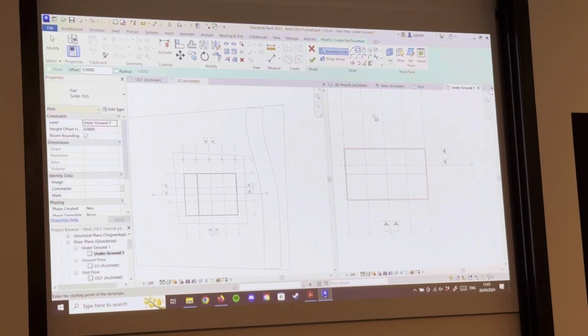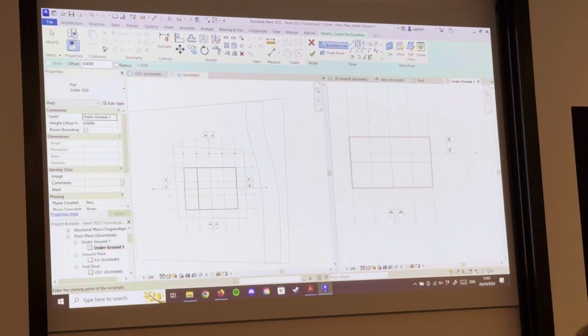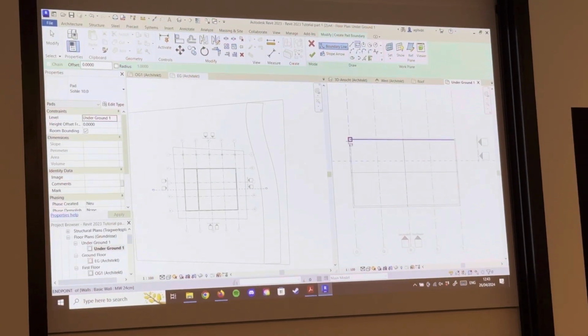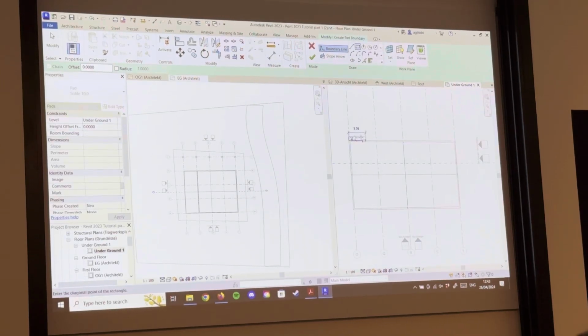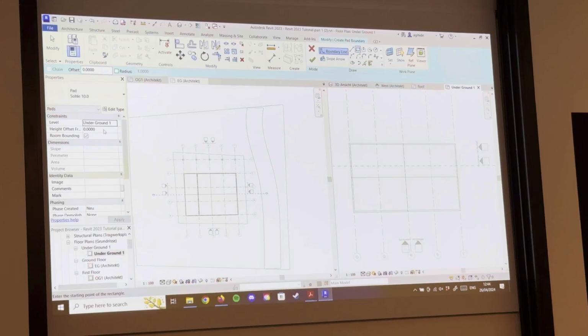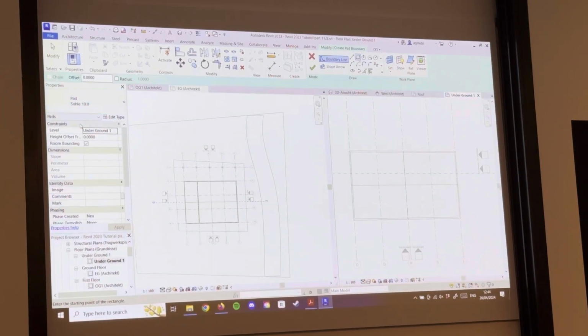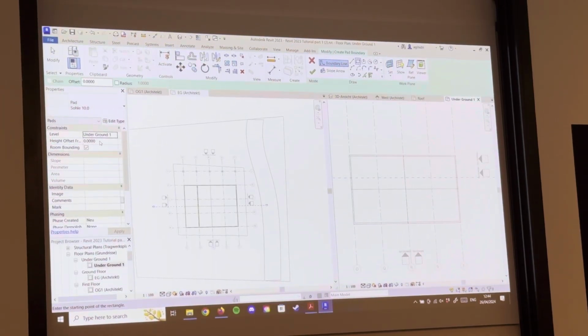We're gonna just draw it now to not lose so much time on it. I guess you understand this part. You can just take a rectangle or something and draw it here. Maybe before I draw, something that would be important to mention is where you are placing this building pad. At the moment, I have it defined under the properties. The height offset is 0, 0.